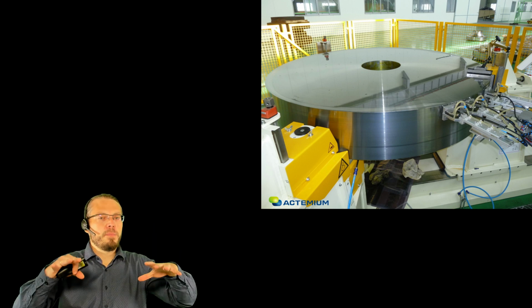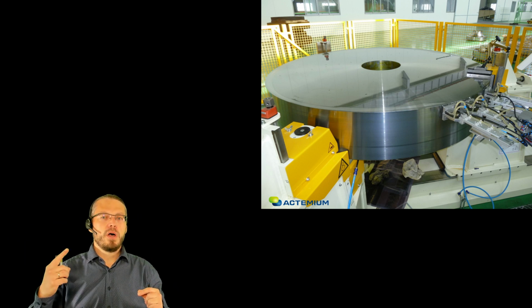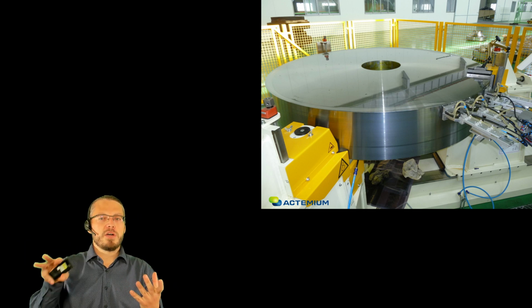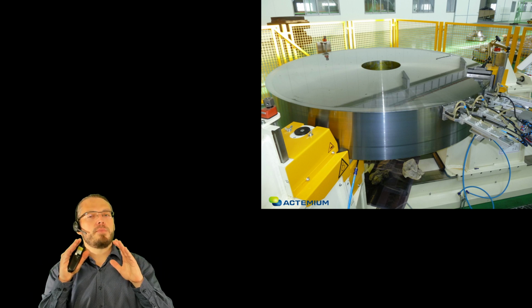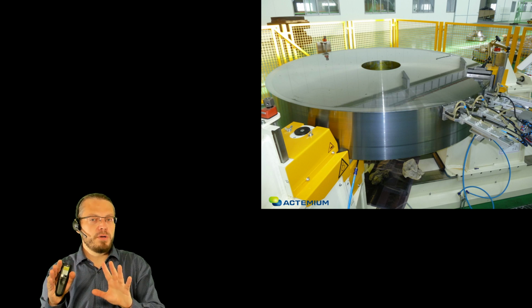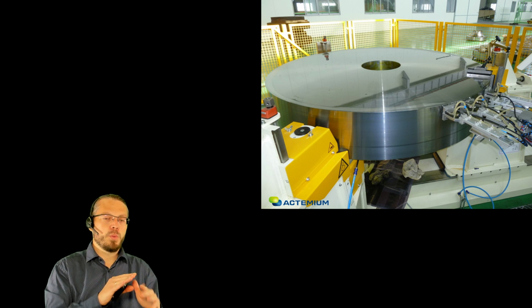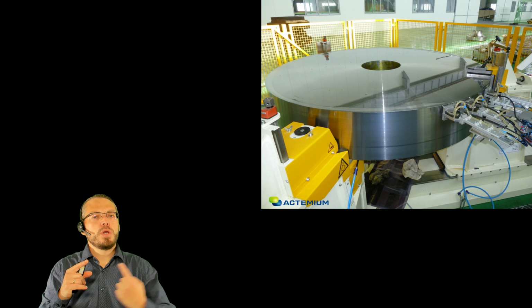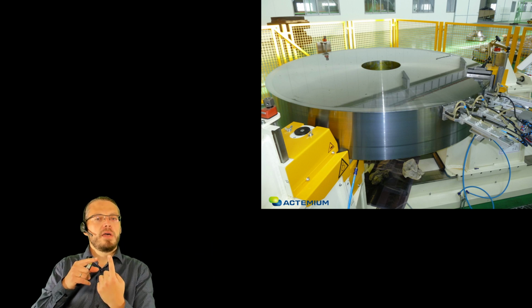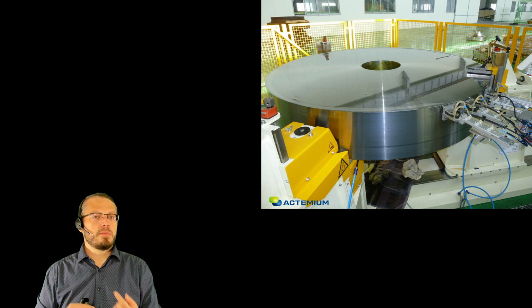So we put that component on the inspection system. We start rotating the disk. We have the probes, which we see here on the right side, which are pressed against the component. And those can be, number one, conventional probes, but they can also be phased array probes. So we can mix them however we like. And once we come around one time, so this is our scan axis, then we index and we go around one more time and we index.